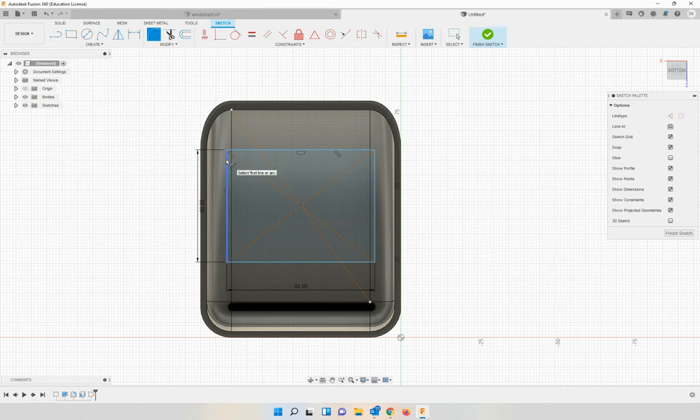Okay, so fillet tool, modify fillet. Doesn't allow me to select the corner since it's center rectangle. Let's change it from 10 to 5. Select our lines not where the construction lines are. Click and click. 5 millimeters on all 4 corners. Good. Enter. Now the offset tool, modify offset.